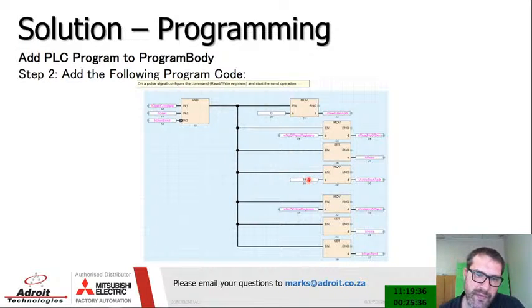So when previously I said you want to write to 40,020, that's where you go and say that's the register that you want to write to. This is where you will put the read register. Okay. So you want to read from 40,001. Remember, there's always an offset of 1. So it will always be 0 that you would add in there.